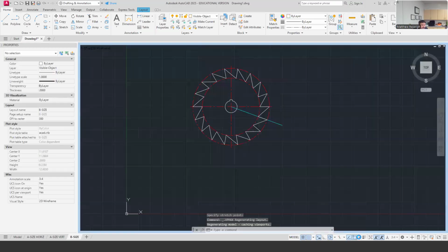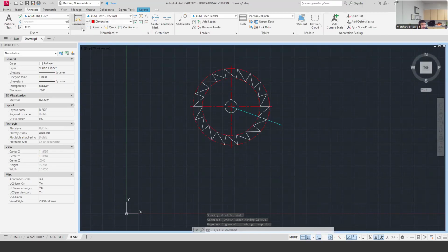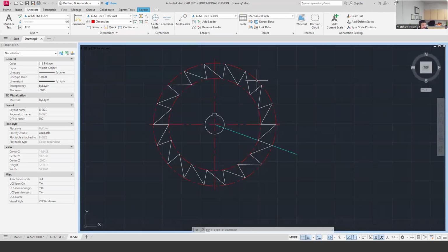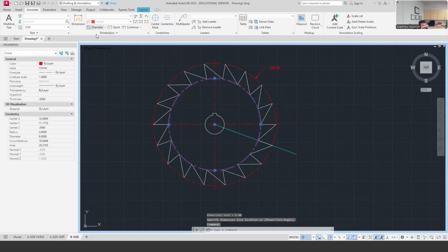Yeah, it's pretty flexible. So here we go. I'm going into dimension now, so I'm on my dimension layer. It is kind of critical to know what these centers are. I'm going to leave those center lines on there to control the troughs and peaks of the points here. So I do want to know what those dimensions are. I'm going to use those as just a diameter dimension, like I've got on my print. I just called this one out at 8, and I called this one out at 6.